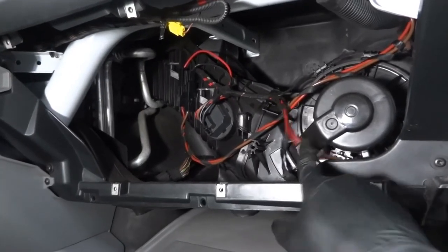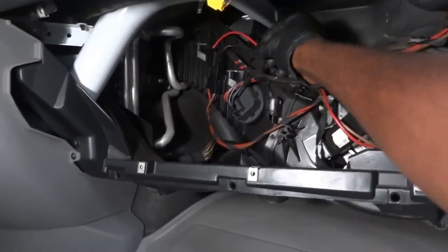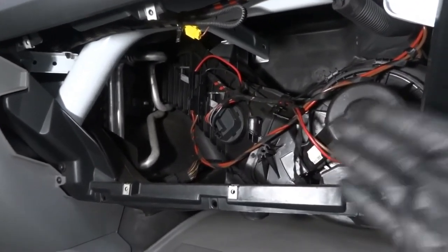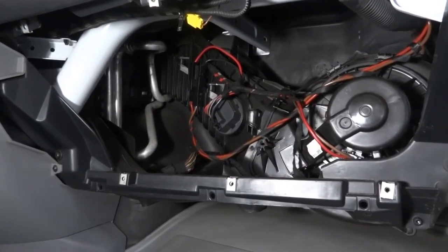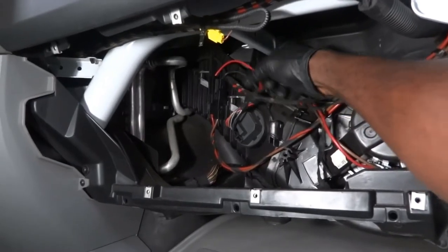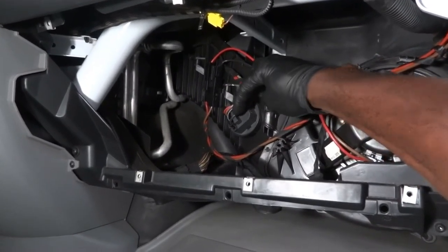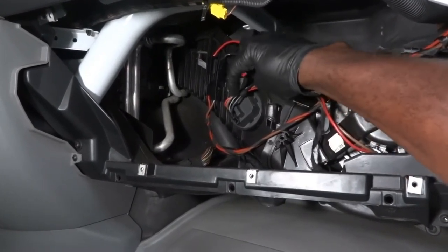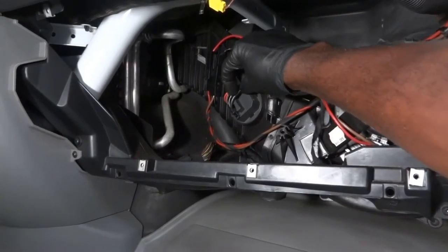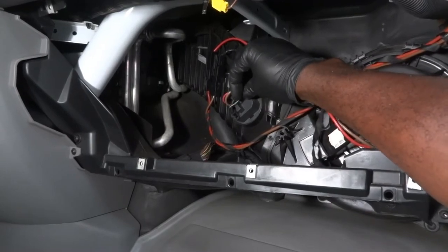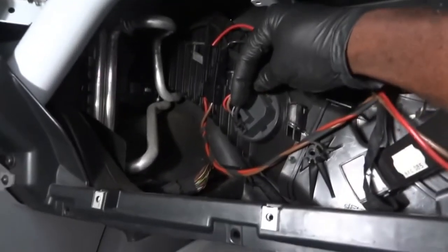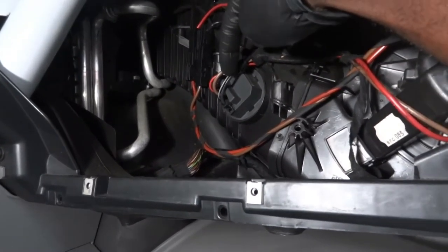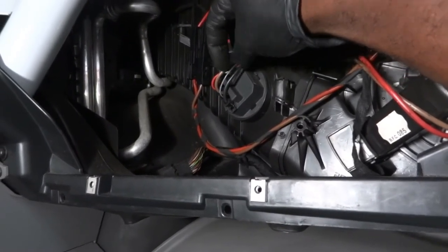Knowing these circuits, this wire here is the red wire, is a power supply. Well, basically at this point, to someone who doesn't know these circuits, you would pull out a wiring diagram so you can find out what wire is what. This black wire here is a ground, okay, and then the red wire here is a power supply, so it's a constant power, okay. And then this gray wire right here, I hope you guys can see this, is the command coming from the AC control module, okay, the air conditioning control module.